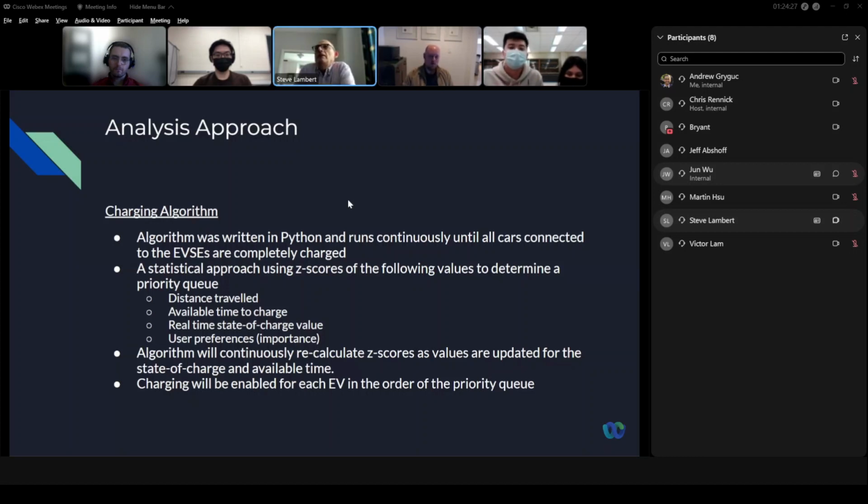Yeah. So it actually depends on how much current is available for the cars. Say, for example, in your house, you turn on your stove, your heater, your washer, things that are high demand load, there actually won't be enough current to sufficiently charge all these cars. So maybe the cars won't be charging at all because they don't have the required current.